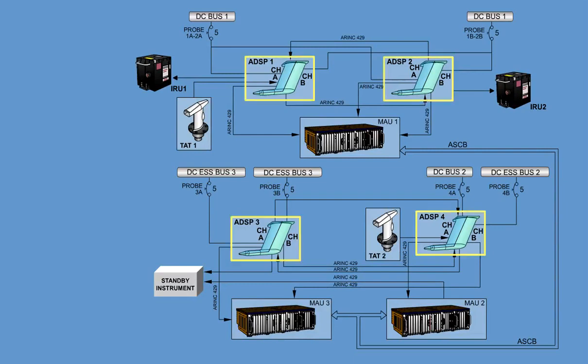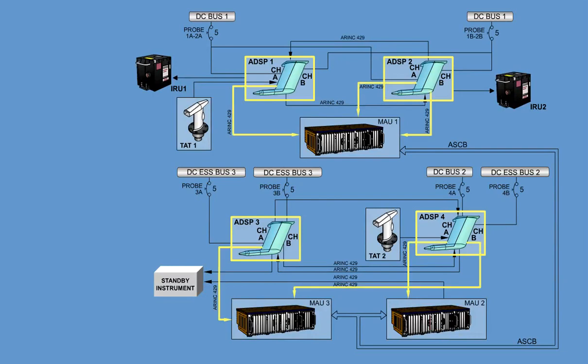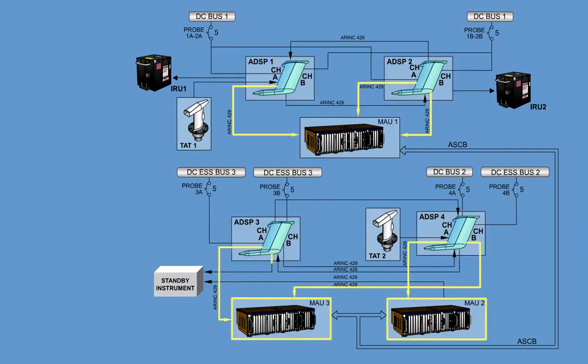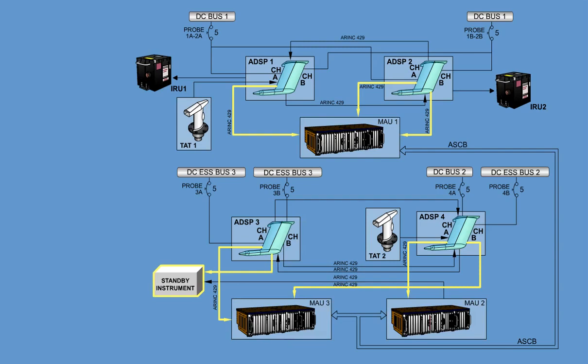The ADC performs air data pressure calculations, which are forwarded to the Air Data Application resident in MAU, or to the Integrated Electronic Standby System, for airplane fuselage effects and sends the information to the flight deck to be displayed as airspeed, altitude, Mach, and angle of attack.